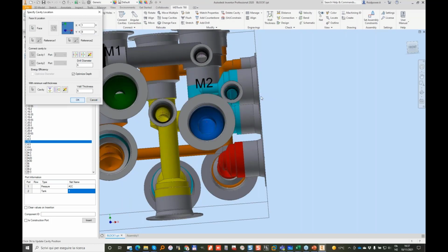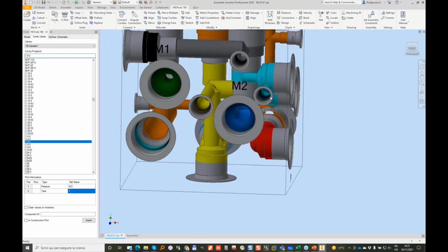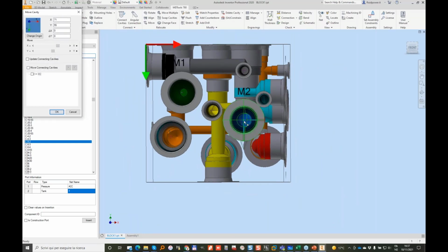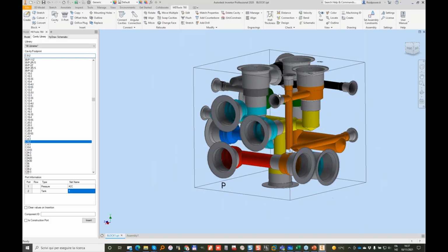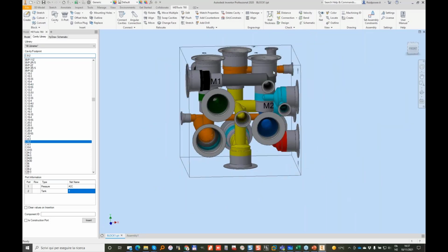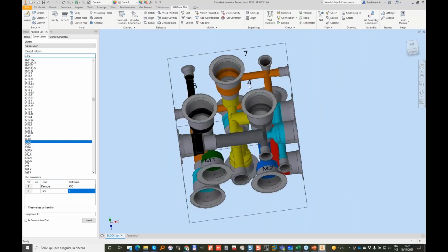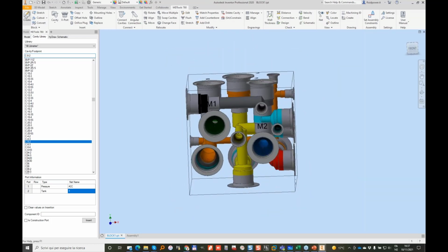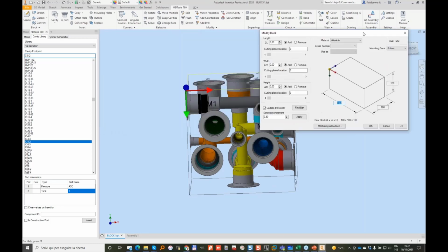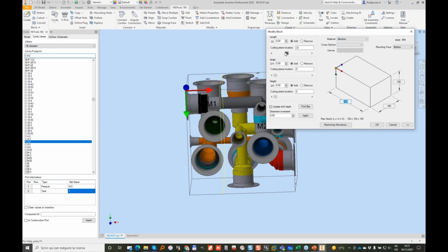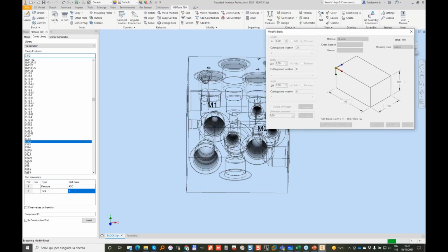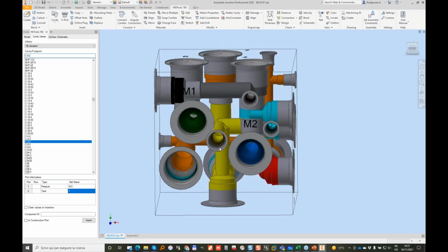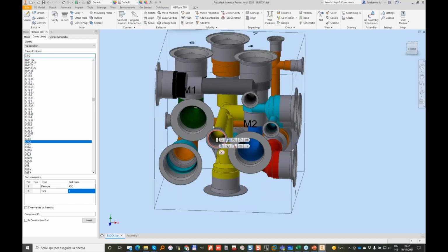Everything would have been much easier if I had started with a larger block. But really, I want to show that it's possible to find the place if you have patience, and if you can see with your eyes how you can make connections. Then it is possible to make compact blocks. And for instance, now that I see here, I could remove material. I could run my create command in the length. Here, I can remove 5 millimeters. So I can even make it smaller now. I move slightly my plug to the right.